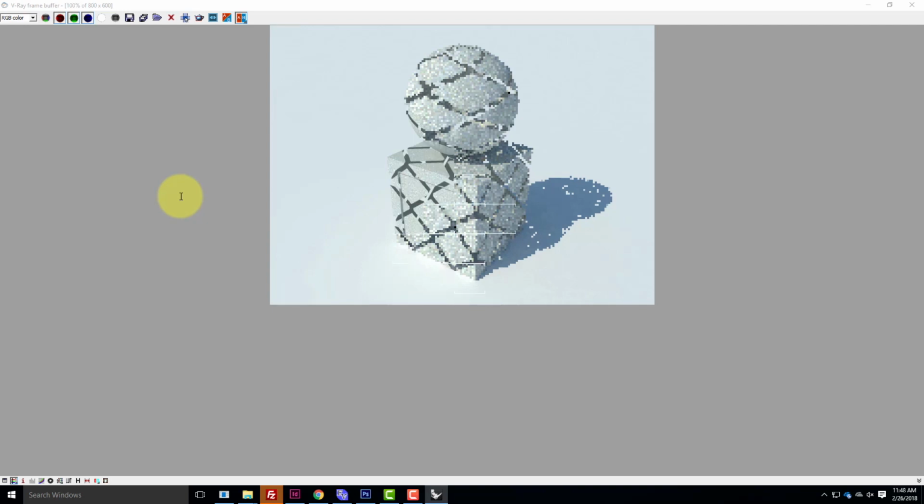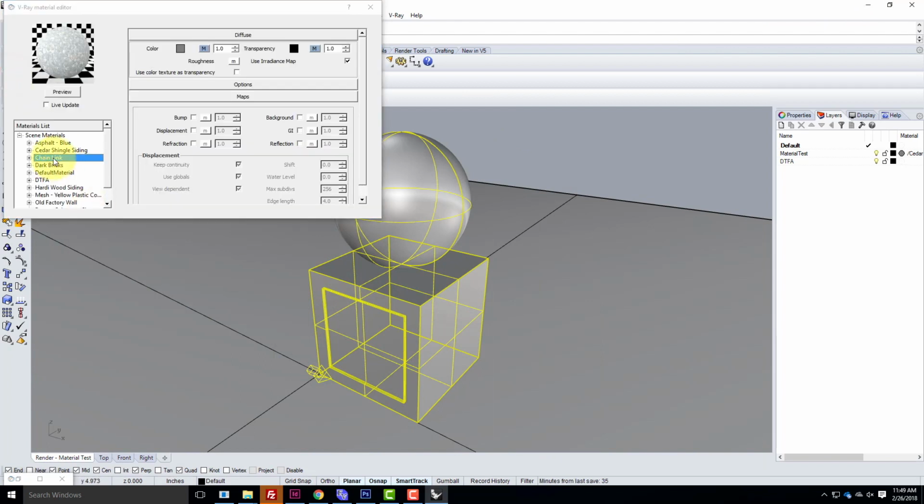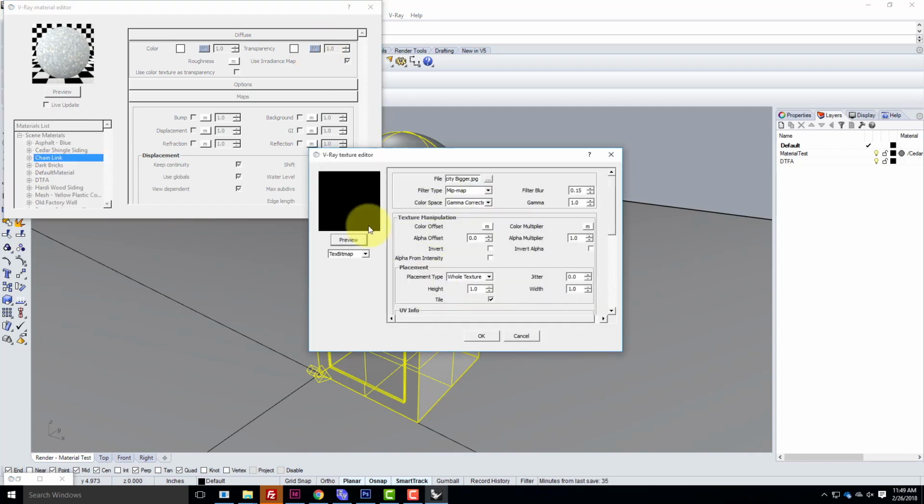So it turns out that it is backwards, so I need to fix that problem. Let me go back into my V-Ray material. Under my transparency map, you should notice that when I first clicked on it, it was a lowercase m, and it's turned into a capital M. Once you have a map applied in one of these, it'll turn from a lowercase m to a capital M, so you can always tell where that's been applied. Let me click on that capital M now.